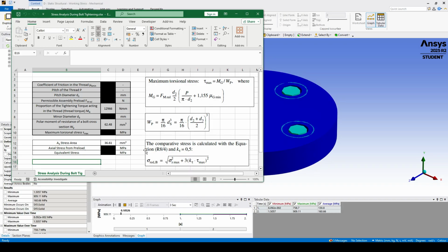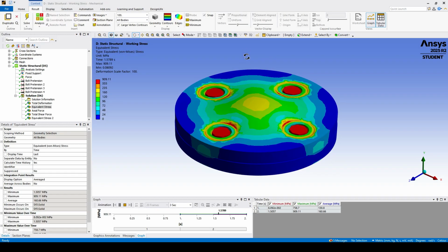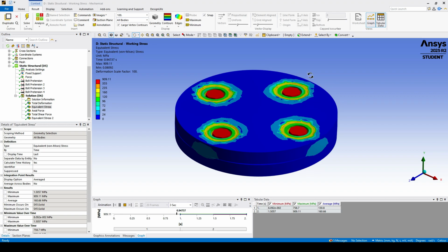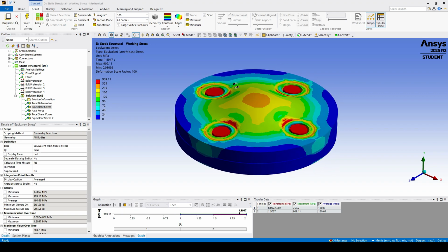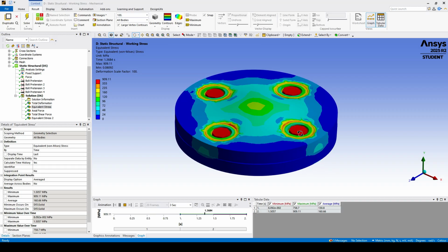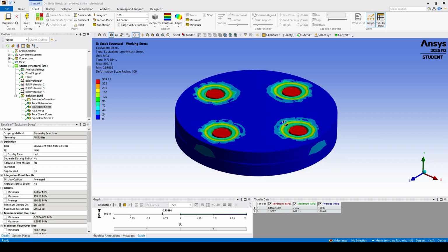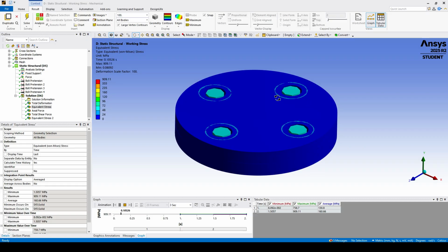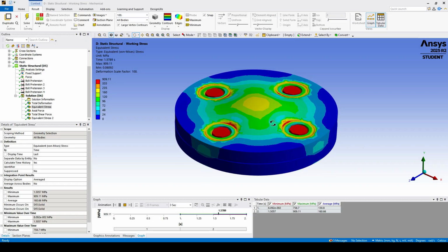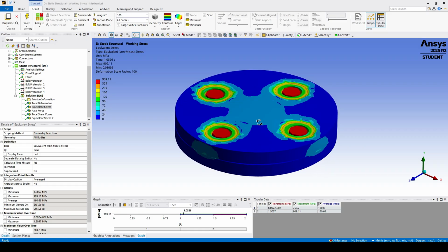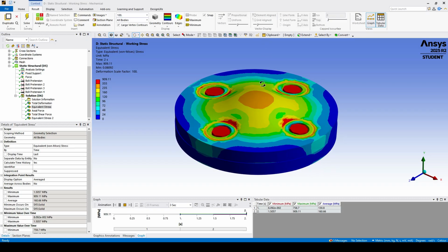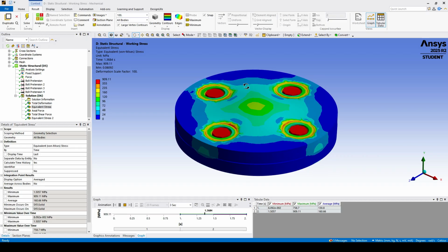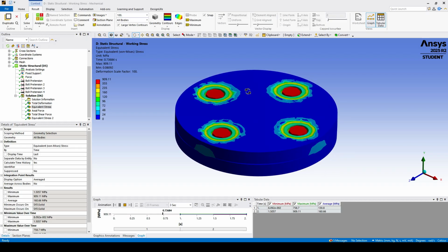So in the previous video, we built this bolt plate connection in ANSYS using 4 M8 bolts with a strength class of 8.8. We then applied an upward load of 20 kilonewton, in this case on the middle, and obtained the stresses in the bolt from the finite element analysis.